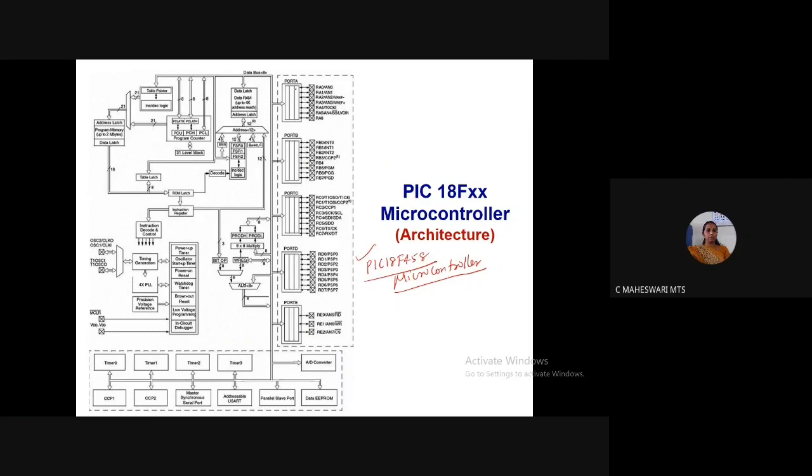So it has port A, port B, port C, port D, and port E. So IO ports, and it has AD converters. Here you have erasable programmable read-only memory, parallel slave port, addressable USART that is your serial communication port, master synchronous serial port, CCP modules, timers, and everything is available here.